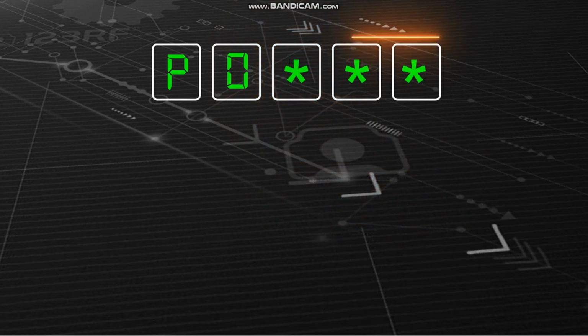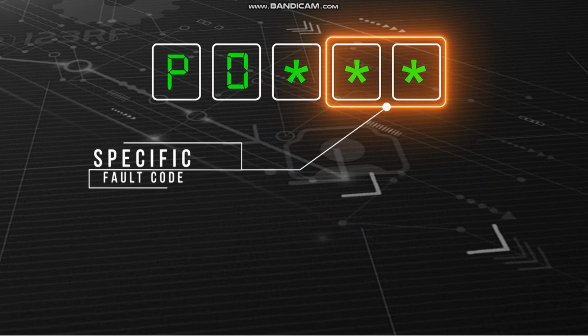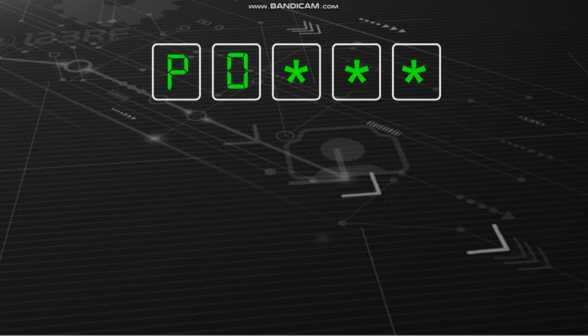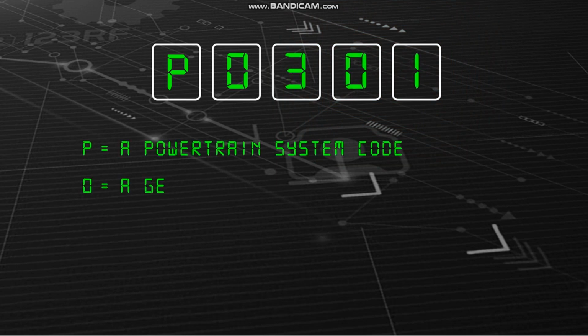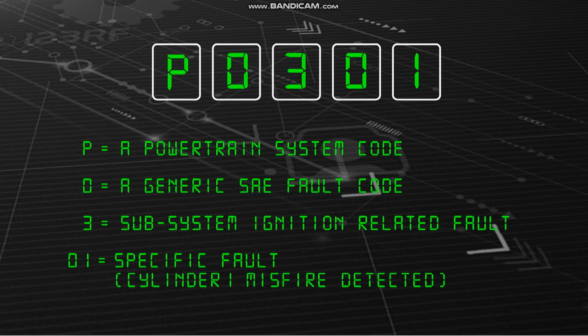The final 2 digits of the fault code are specific numbers designated to the actual fault identified. So, if we see a fault code P0301, we can interpret this as a generic SAE powertrain fault, localised to a misfire in cylinder 1.